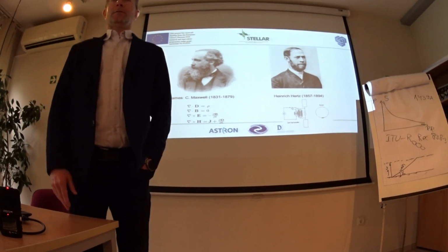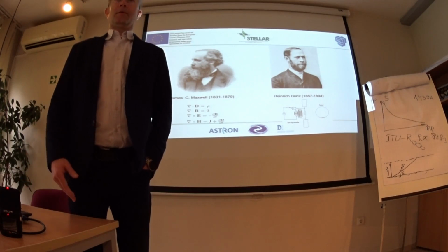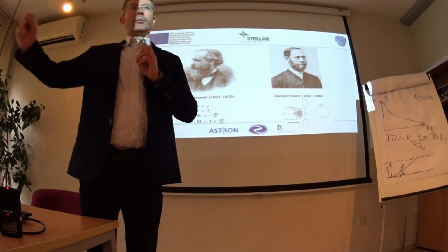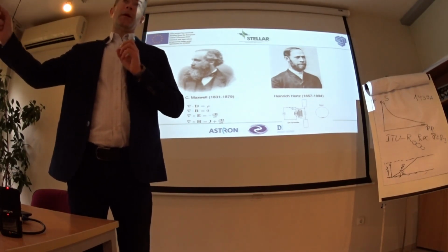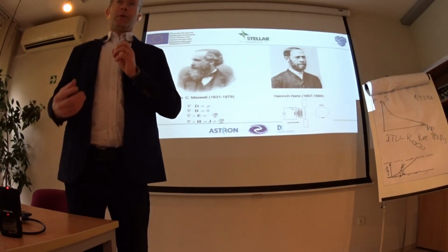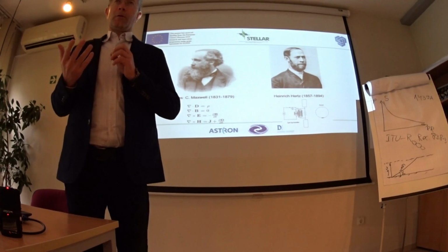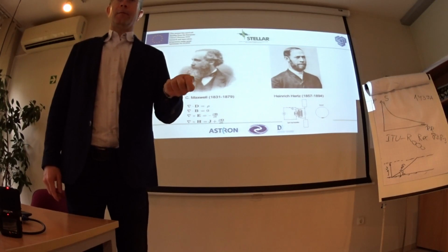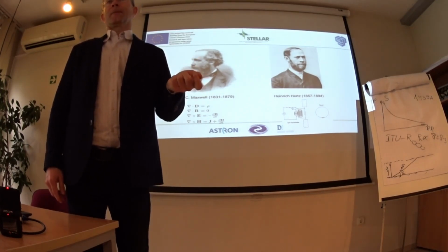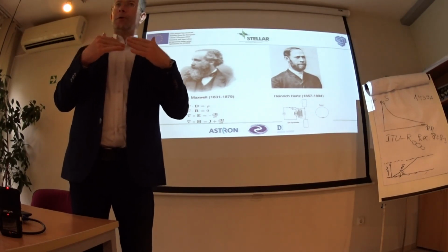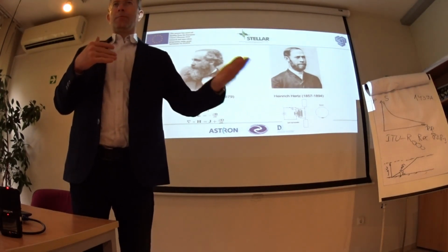like TV antennas. If something happens with the TV, who cares? Nobody. But if the antenna is for radio relay, then a lot of people rely on it. So all measures must be taken in order to provide a constant link. And because radomes are expensive and they degrade the performance of the antenna, it's up to an engineering decision whether one should be employed or not.